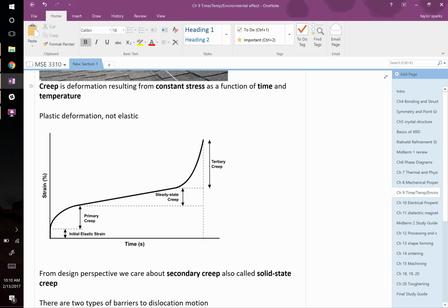There's going to be a region where it's rapidly increasing up to a point, and then it reaches this is primary creep. It's going to reach a region where it's now constant rate of creep. That's the steady state region. And right before it fails, it starts to take off again. So there's these 1, 2, 3 regimes that are characteristic of creep. Okay? It'd be great to model all 3 of those regimes, but it's hard to. So instead what we model is the second regime, right? Because it's linear. It's something that we can control a little bit. So you could say, hey, if you know the slope here, and this is typically a log plot, yeah, it must be a log plot actually, then it might go from, I don't know, a couple days to 5 years of the material, right, before it breaks. So this is a nice time to be able to model what creep is doing there.